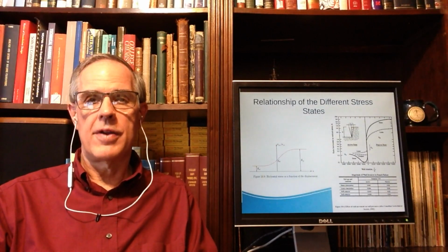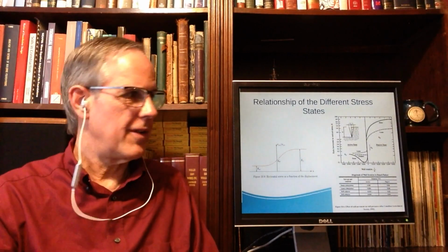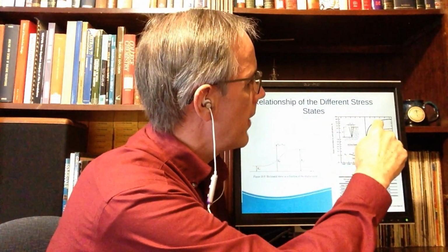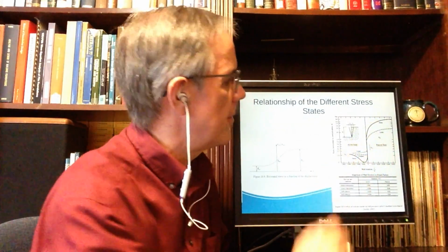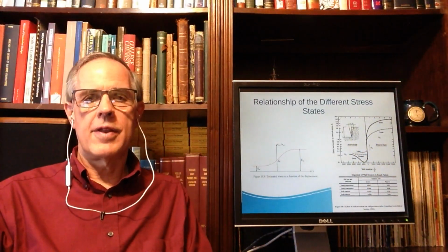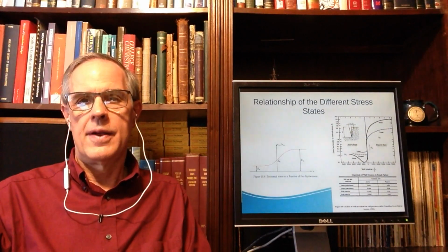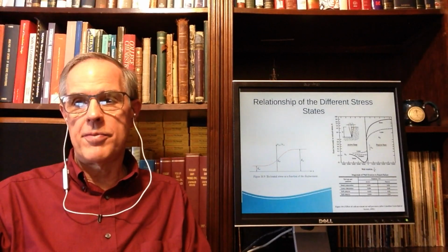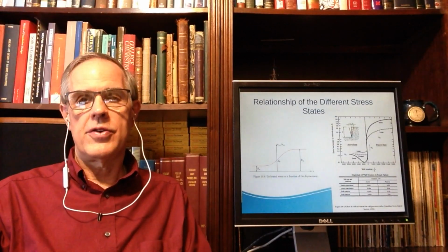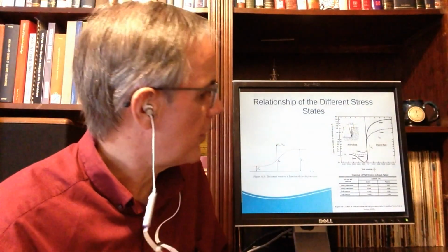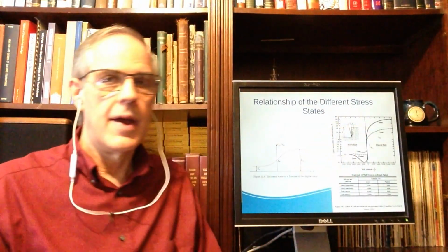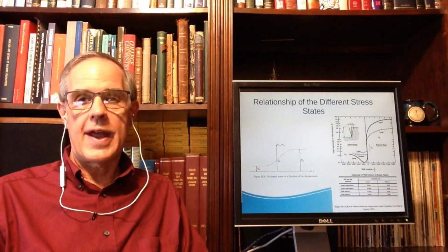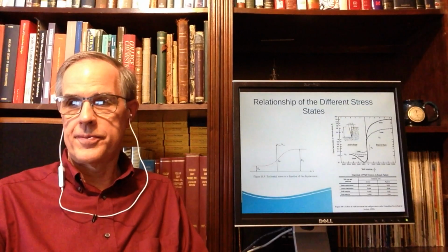Like I said, when we get to sheet piling, the software we use actually does, because you come here and then you take a straight shot up there and then over is the way it models it. It simplifies it the way we do when we make the elastoplastic model. So that's something you should be aware of, and that diagram is important because eventually you're going to have to estimate using this particular diagram how much wall deflection you're going to have before fully active or fully passive pressure set in.